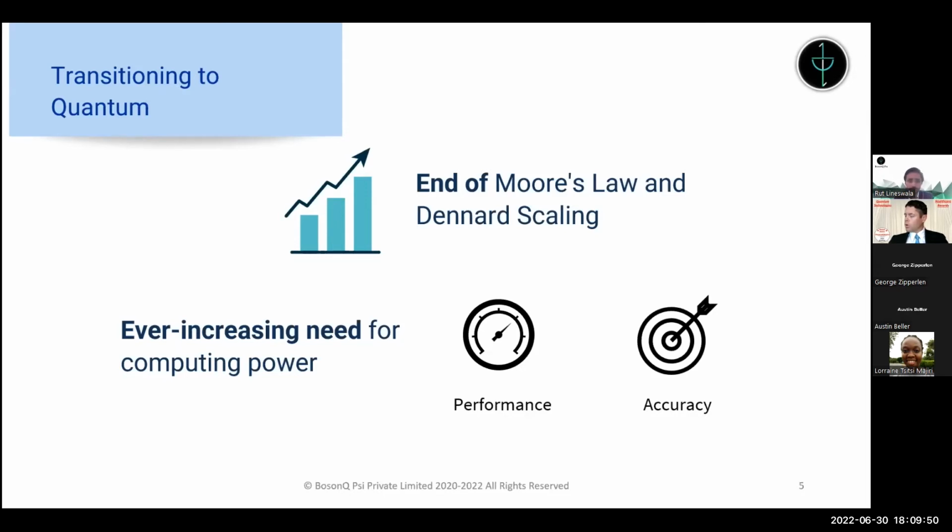And there's also another aspect to it, the Dennard scaling, which is essentially looking at the power density in a specific chip. As the number of transistors in a single computing chip increases, the power density also increases, and that can cause a lot of problems due to overheating. Well, that's mainly it, to be honest, overheating. We're talking about producing so much heat that the efficiency of the transistors themselves decreases, and the overall power input that is required tremendously increases.